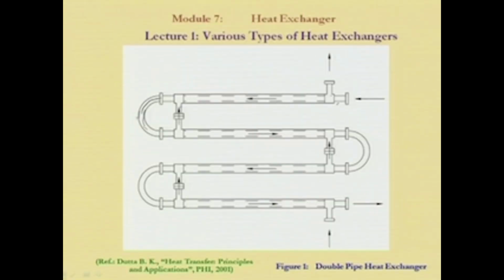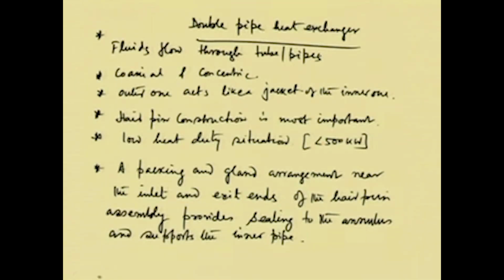Now, also we can say that opposite ends are joined by U bends. That means, you can see there that this portion is the U bend and it is separately joined here. This is the tube, this is another tube, and the U bends are joined with a flange arrangement. That is an easy construction for the tubes.